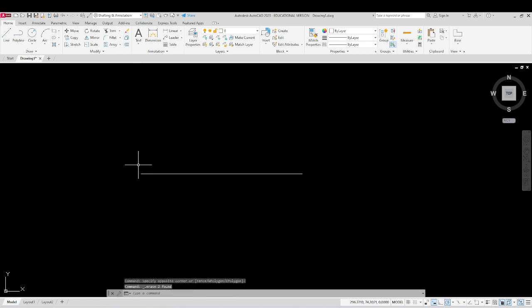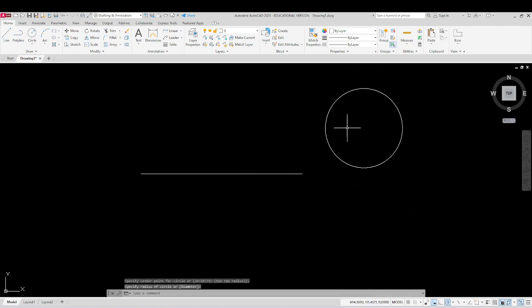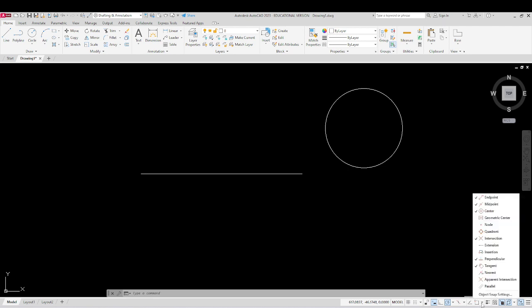So to select the end point of a line or the midpoint of a line, we use the object snap. What it does is it snaps the geometrical entities of the object. Geometrical entities like end point, midpoint, or center of a circle, quadrants of a circle, center of a rectangle, like this. All these geometrical entities it will snap. If I select the drop down of this object snap, I can see a lot of geometrical entities like endpoint, midpoint, center, geometrical center, node, intersection, etc.